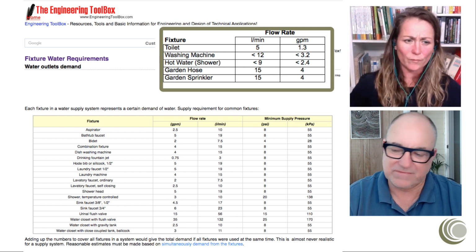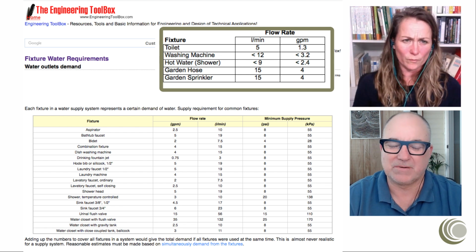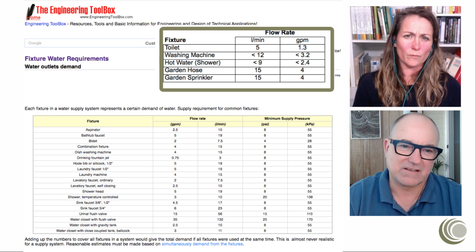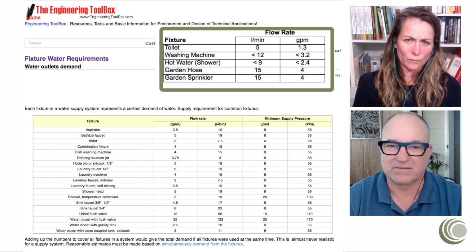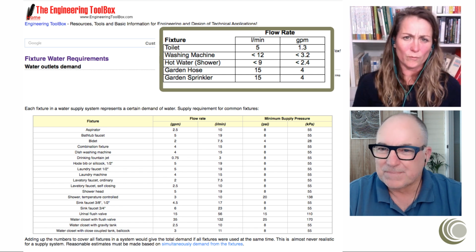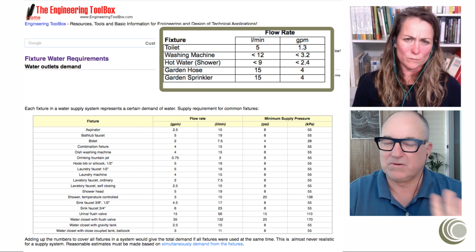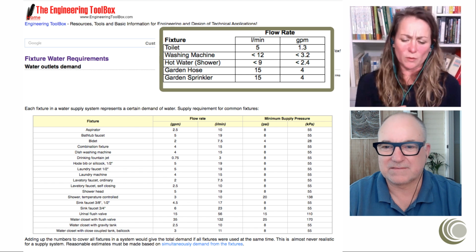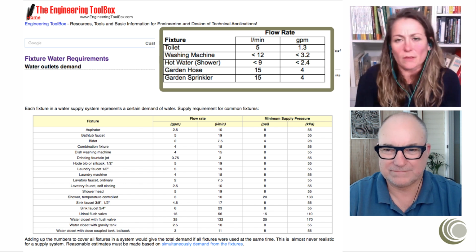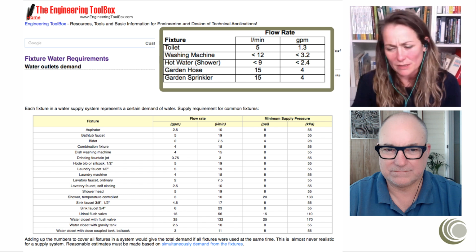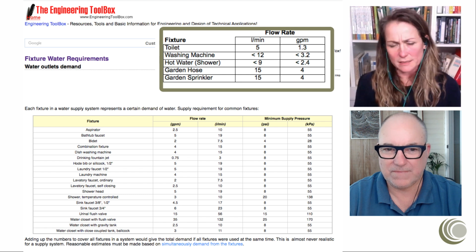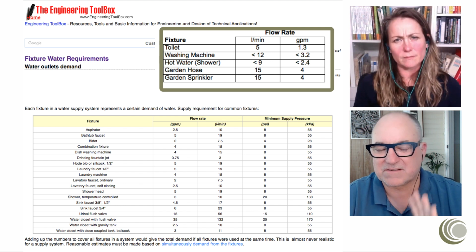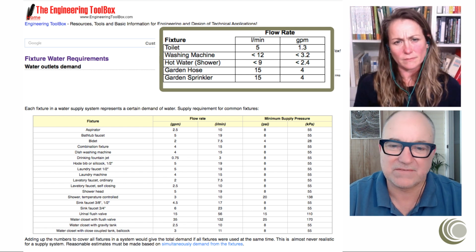That's why if you're going to put a very fine filter, you don't put it at the pump, you put it at the end use where you really need it. So in our house, we've actually got the 0.1 micron filter only on the drinking water tap, because there's no point pumping water through that filter for the whole house. It's just not needed. So, do you find your drinking water tap has a lower pressure, it comes out a little bit slower than maybe your hand basins where you're washing your hands? Yeah, it does. So you have that pressure and flow rate loss because the pump's trying to push water through that filter.